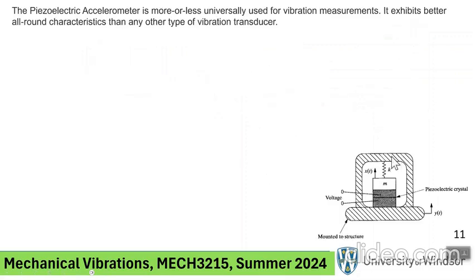Okay, all right. So there are a few comments that I would like to make about piezoelectric accelerometers. I'm going to read this so that you don't miss anything important. Here is a modern piezoelectric accelerometer. There is no damper, let me put it this way. And this also provides some kind of stiffness. It could be that in certain designs, this K is actually embedded within that piezo ceramic.